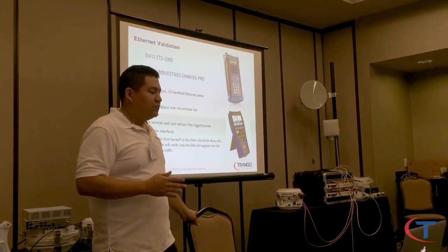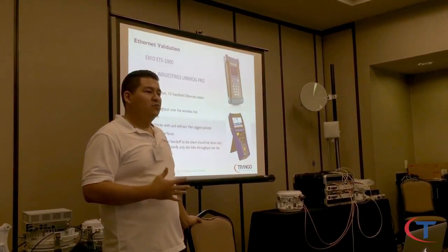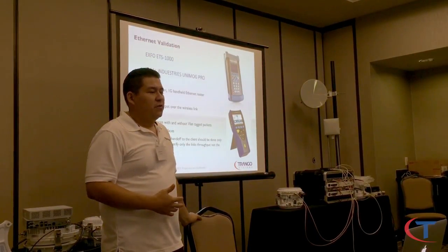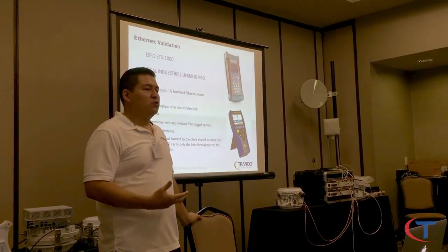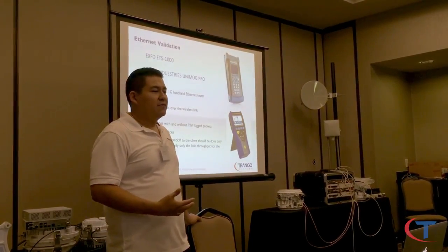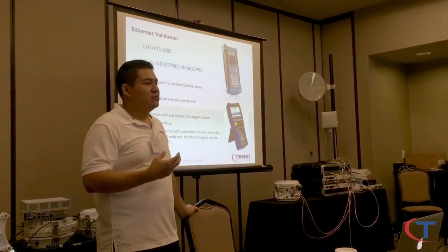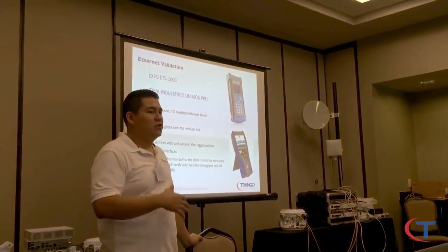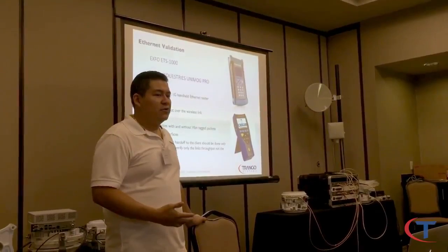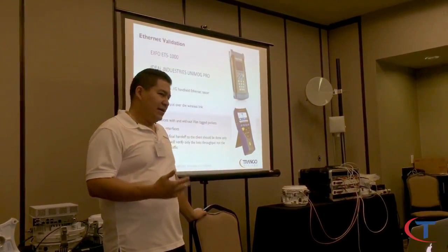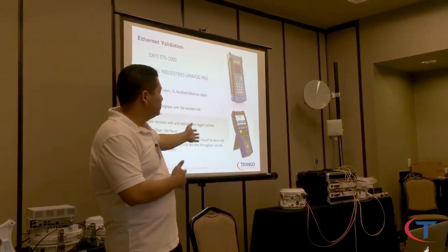On this note, I do not recommend testing the link using iPerf. Okay? iPerf is not the most precise tool we're going to use for a wireless connection. The reason why is because you rely on the software of the computer, the CPU processing power, and unfortunately the results are never really consistent. Based on the UDP packet size as well, you will have more or less actual throughput. And it's not depending on the radio, it's actually on the computer's connection to the switch, to the network. So iPerf is not what we encourage or recommend at all. If anything, we want you guys to use the actual handheld generators.